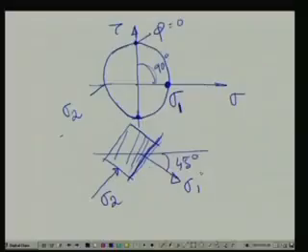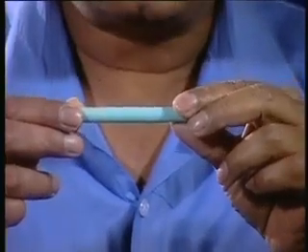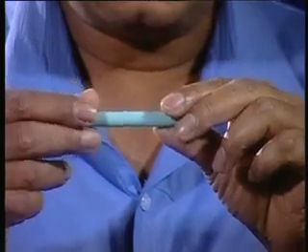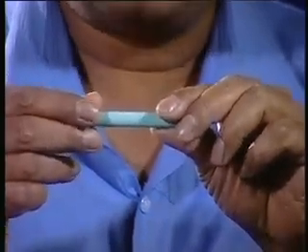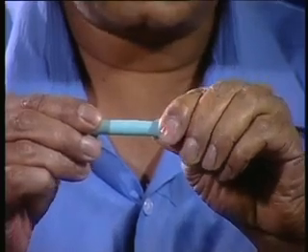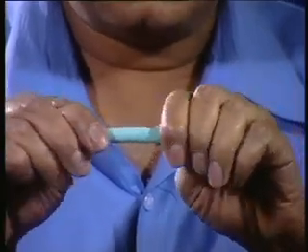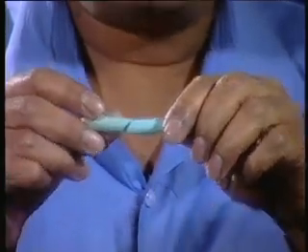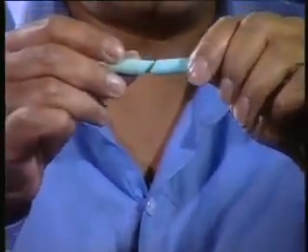See, I have chosen a material, chalk, a simple chalk, and we apply a pure torsion onto the chalk. Just you can see that if I apply a pure torsion, then it is a little hard, so just see it has broken. Can you see the broken portion, how it has failed?